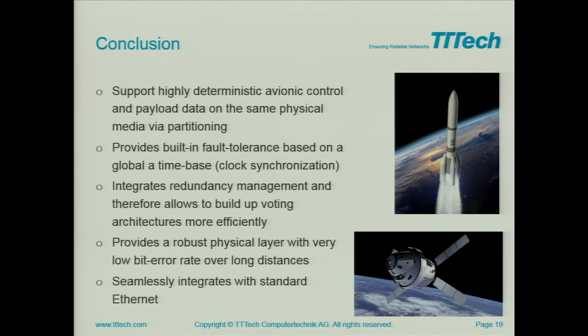It provides built-in fault tolerance based on the global time base, so you have a global fault-tolerant synchronous time, and integrated redundancy management. The full redundancy management is handled by the protocol. The only thing you need to care about is the application data and the application voting.